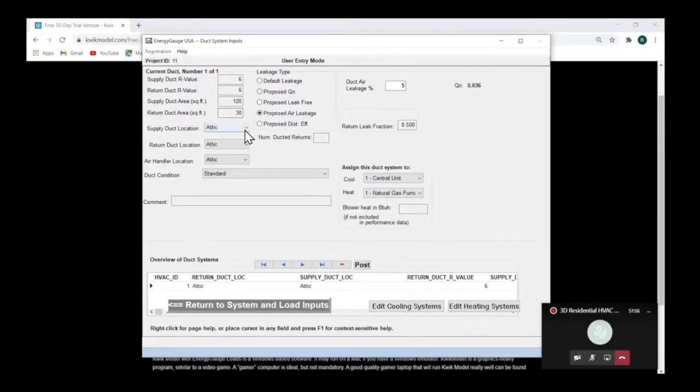That's usually good enough. It'll ask you where your ducts are located, where your air handler is located, and then it'll ask you about duct leakage. How are you defining duct leakage? In California, if you're installing a new system, the maximum allowed duct leakage, which is tested in every house by a third-party inspector called a HERS rater, is no more than 5%, okay? For existing homes that have been altered, if you're just replacing the furnace or just the air conditioner, the maximum allowed leakage is 15%. So that would be a reasonable number to put there.